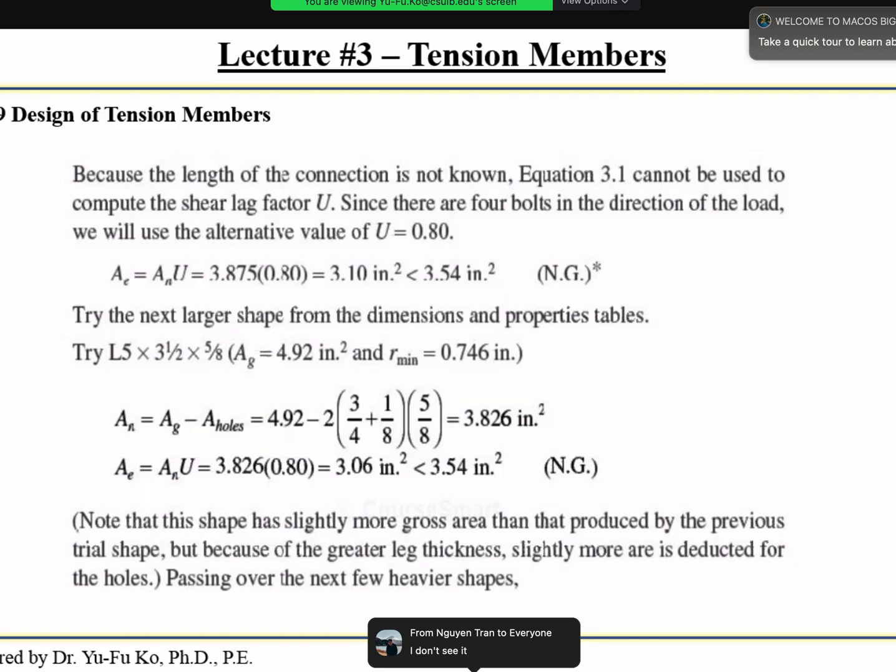Yeah, there's a Z dash Z for that here. I found the minimum R to be 2.30. For angle, it doesn't matter. As long as the angle is unsymmetric, you always have XX, YY, and ZZ. It's not a symmetric section at all. No matter even if both sides are like an L6 by 6, even if your two lengths are the same, it doesn't matter as long as it's non-symmetric. So for an angle, okay, I was getting a little confused there.